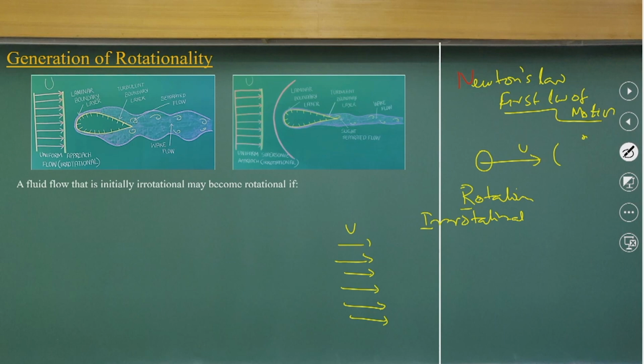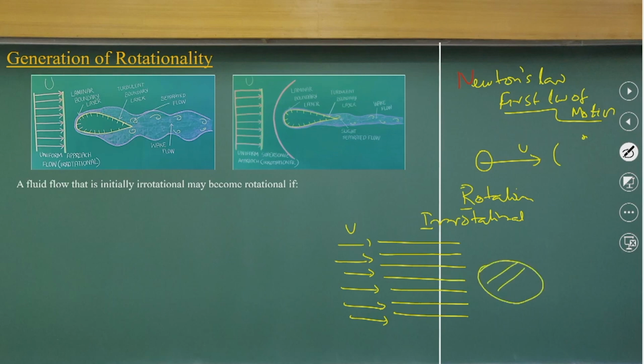Here we do not visualize body movements or object movements; you have to understand it conceptually. For example, wind movement having uniform velocities. When you have uniform velocities, the nature of irrotationality does not change, unless you put an object here, which will create boundary layers, low velocity viscous zones, and create vorticities. Then it will change the irrotational properties, and it will go to rotational behavior.